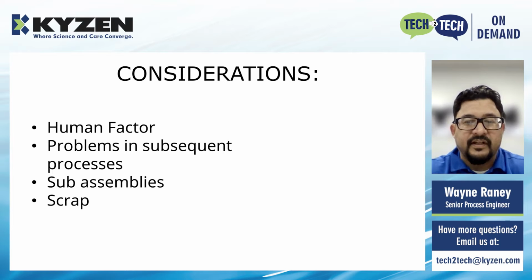If the inspection that is carried out is not correct, then the batch can be considered good, even though the parts are still not clean. And this can generate problems after the wash process. As an example, if one of these tubes is part of a subassembly to a welding process, the presence of oils in the joints will affect the weld, causing this part to fail and produce scrap.